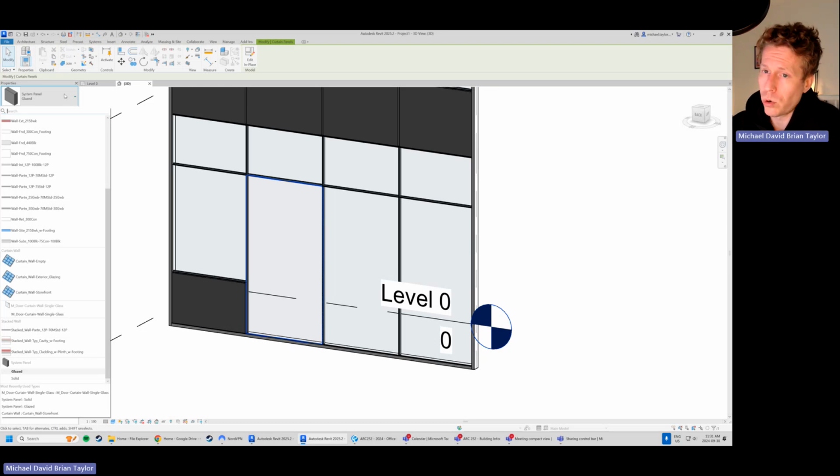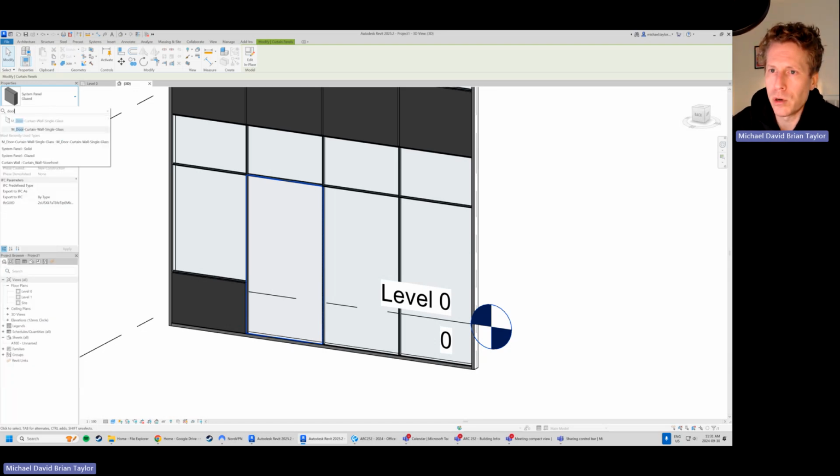There's only going to be one door here because there's not going to be typically doors within our wall type selector for walls. I realize that's confusing. The easiest way to see it, we can see door here. So door, curtain wall, single glass. If you would prefer, you're seeing all these wall types, type door, and we should have door, curtain wall, single glass populate. Boom.